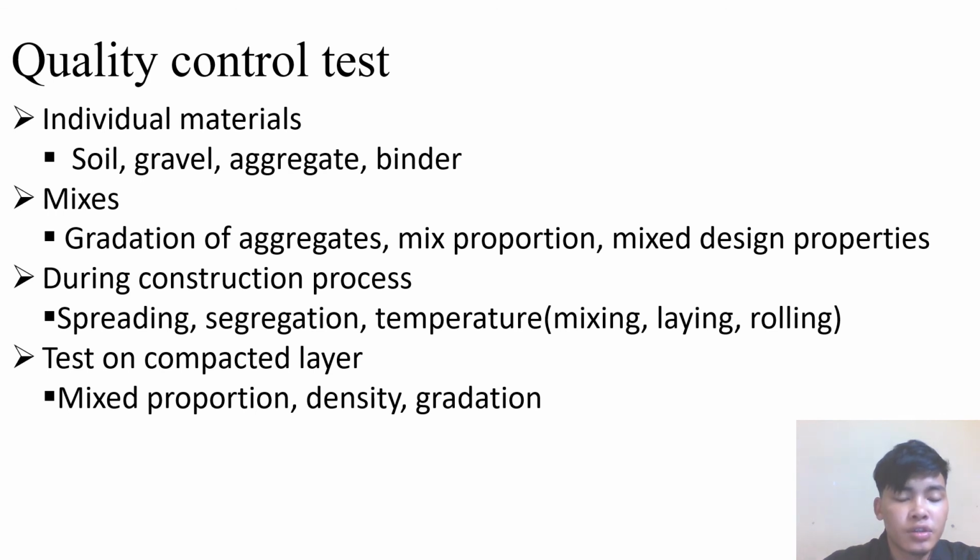Quality control tests during the construction process: spreading, segregation, and temperature. Tests on compacted layer. We must be doing tests for mix proportion, density, and gradation.